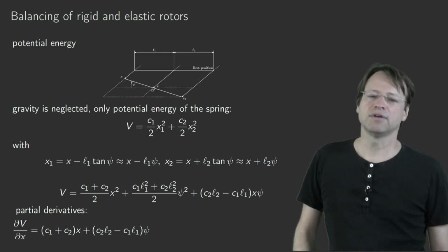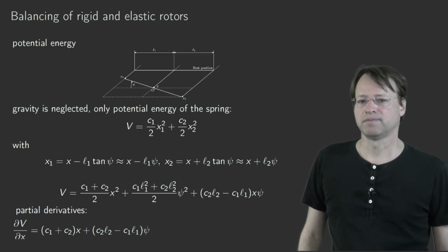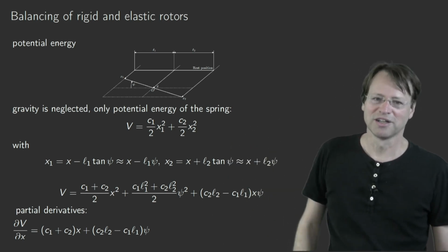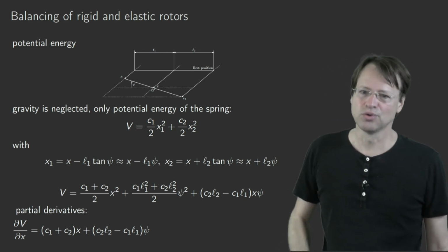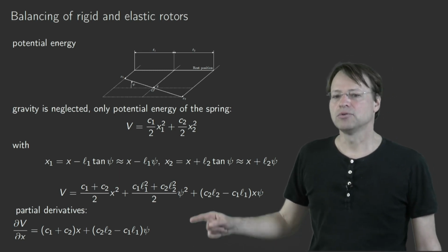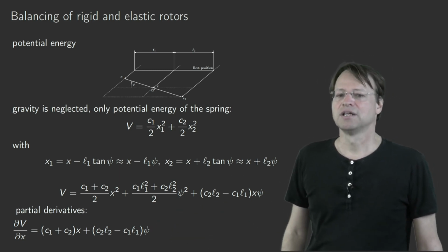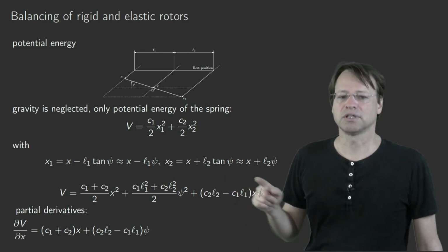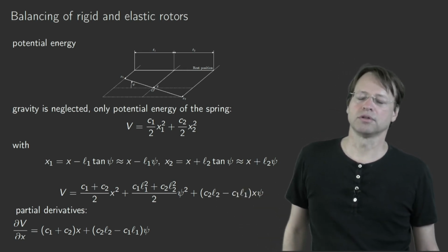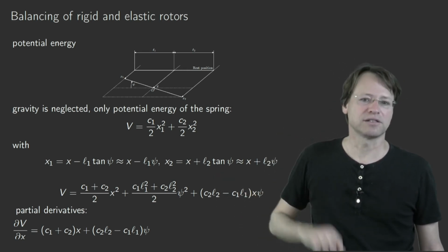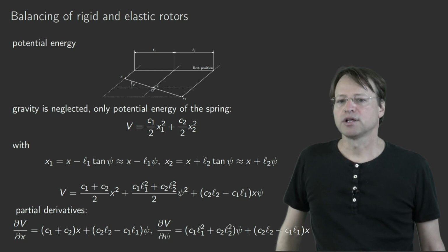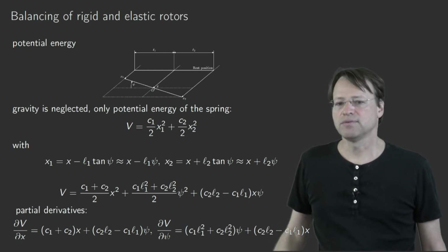Already here you can see that the equation of motion that we will obtain will be coupled, because this is the contribution that should matter for the first and second Lagrange equation that we will obtain. That would be the Lagrange equation that governs x. And you see that in that equation that governs x, psi appears from that mixed term here. Yeah? So again, that rotation relates the two terms, or couples the two equations of motion, a very classical result in dynamics.